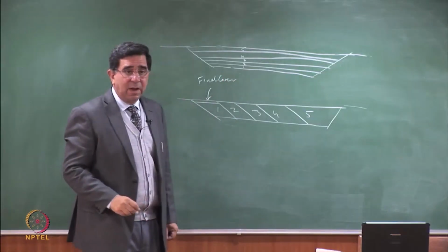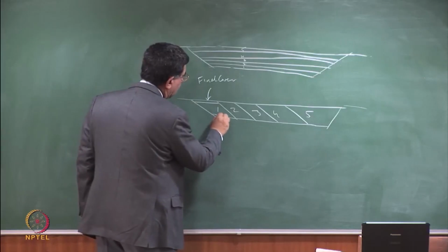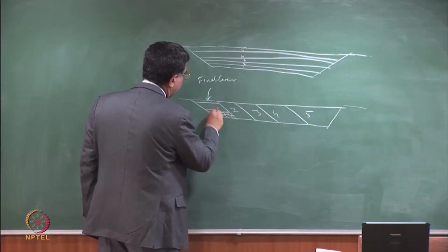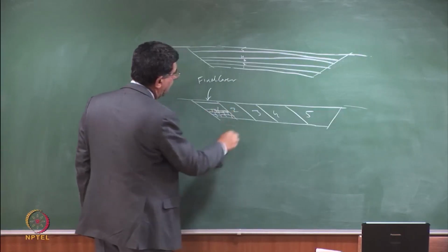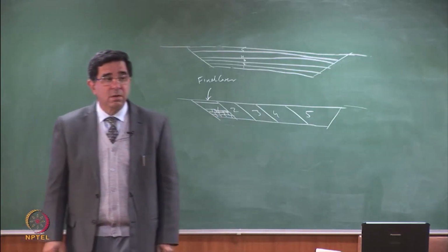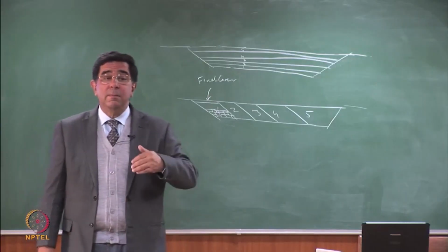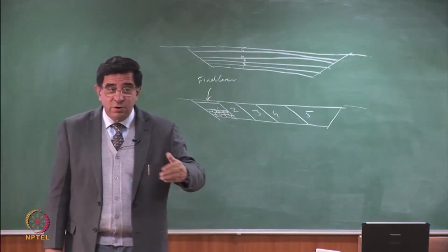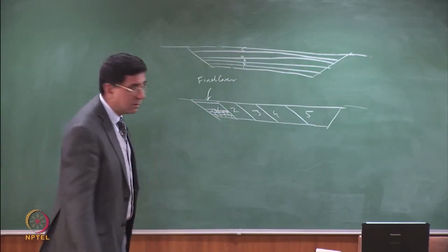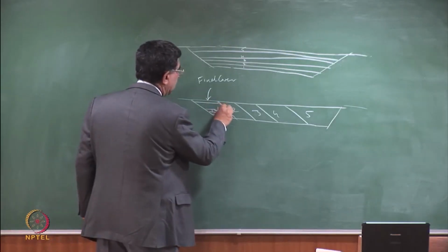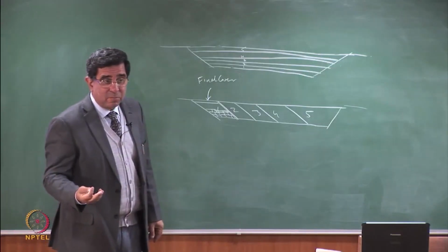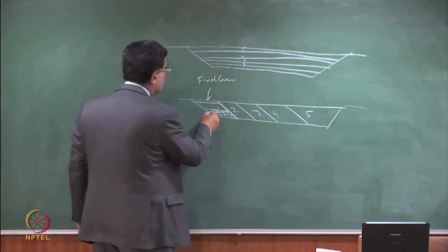And I have my daily cells here with their daily covers, okay? Is this the final cover, the slope? It will be more than the daily cover because it's going to remain exposed for 1 year till this cell fills up. So it is intermediate cover. So this is final, this is intermediate because it's not going to be the final cover. So this is daily.